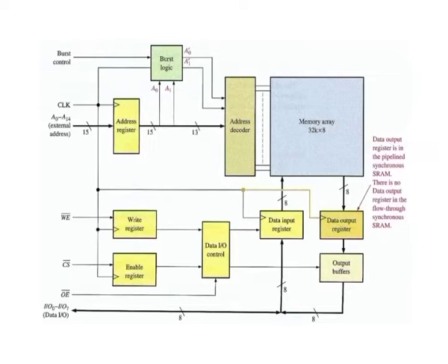The basic difference is that the synchronous SRAM uses clocked registers to synchronize all inputs with the system clock. The address, the read/write input, the chip enable and the input data are all latched into their respective registers on an active clock pulse edge. Once this information is latched, the memory operation is in sync with the clock.